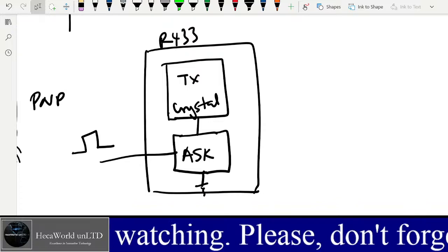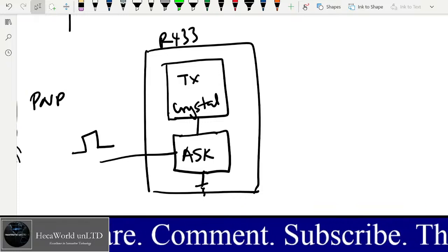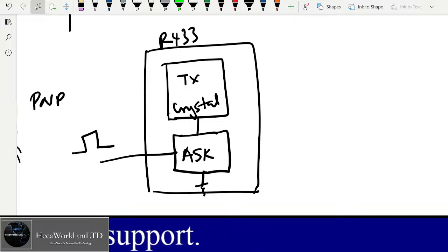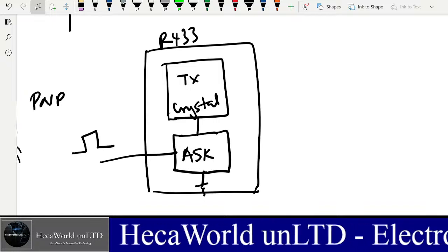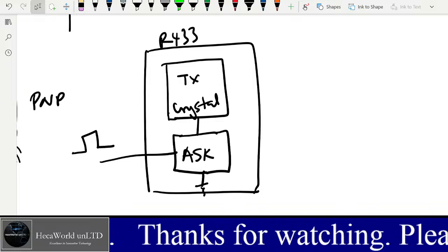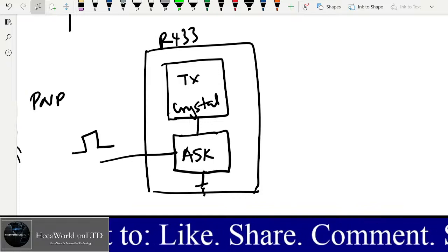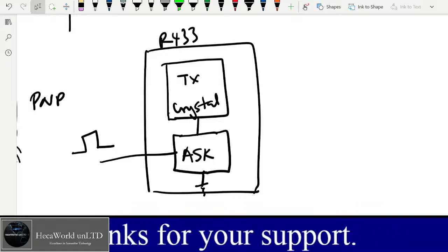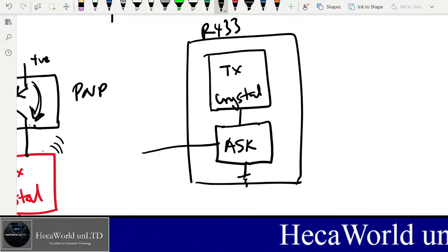Let's say there's a light source. Let's say there's something that always produces a signal, but you want that when the signal is out, you want to transmit or send a warning. Then you want to use maybe an optocoupler or maybe a PNP opto transistor to control the signal, so that when the signal is removed, it goes negative, and then you turn on the transmitter, so you save power from the transmitter. So what I'm going to recommend you do is, let's just delete this.